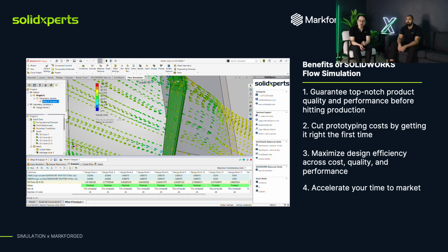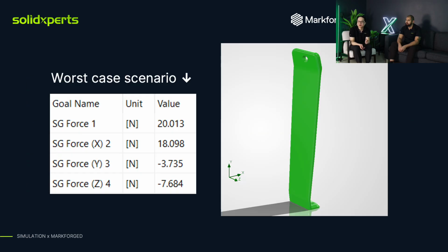So what are we going to take away here to stay conservative? We're going to take the worst case scenario we obtained. So we noted here, following our tests, that the wall representing the bodywork contributed a lot to reducing the drag force. So we're going to take the worst case, which is a safer case. That corresponds here to the case where we have the piece as is, without the bodywork wall, with a drag force of about 20 newtons. So from here, I'll take these results and hand everything back to you, Lillian.